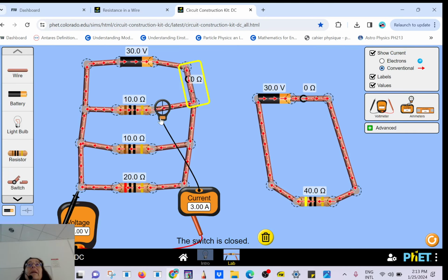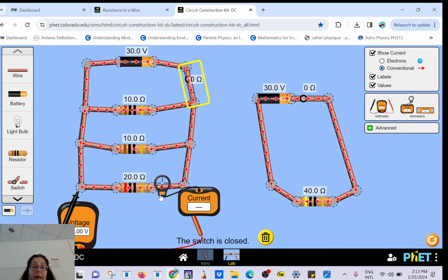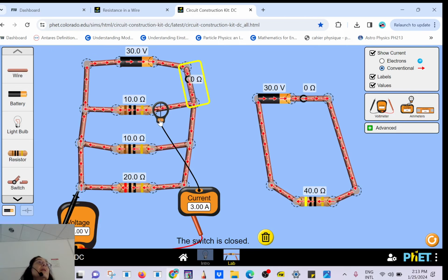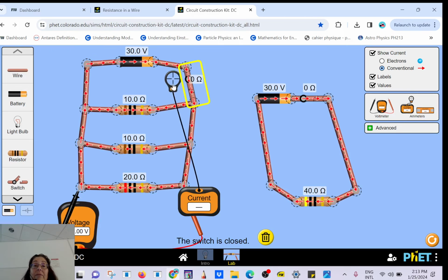So the price to pay, there is always a price to pay. If you have 3 and 1.5, what do you expect? How much do you think you're going to drain from the power supply? It's like water flowing, okay? So you're going to have 1.5 gallon here and 3 gallons and 3 gallons. So altogether, how much do you need? 7.5. Very good. So 7.5 amps.